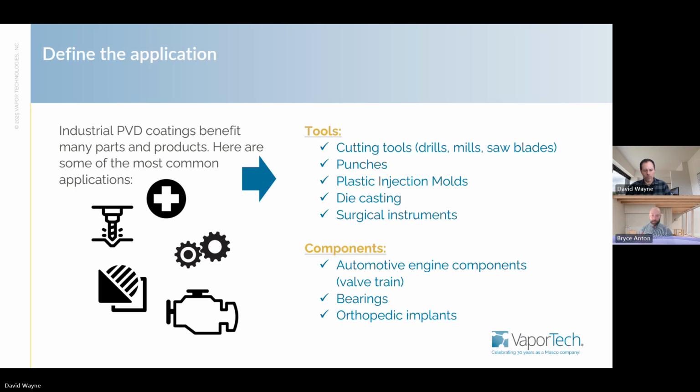And the more we understand the environment that it's put in, the limitations. Some substrates or materials that need to be coated have temperature limitations. They're hardened steels. They can't get above a certain temperature. So we may need to choose a certain technology over another one if we need to manage thermal requirements, or what temperature it's going to be used at. Does it need to be a higher temperature material? Do we need to make something that's going to resist oxidation? Is it something where the coating may have a corrosion situation where the environment is very difficult? So we always have to get in there and understand where that's going to be used. And we've got a whole list of different coatings that have really established properties that we can jump in and work to.